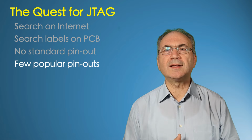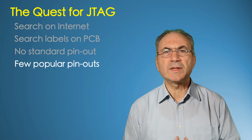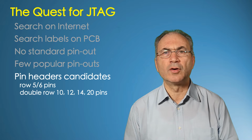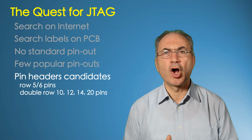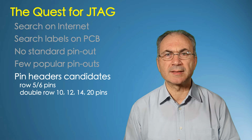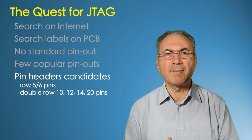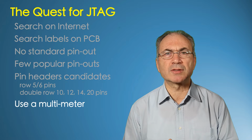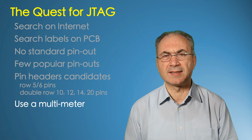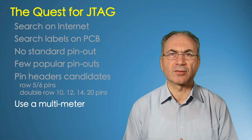If we don't find any JTAG pin label on our board, we start searching for pin headers arranged in a single row of 5 or 6 pins or in a double row of 10, 12, 14 or 20 pins. When we have found the pin candidates, we can use a multimeter to find the possible pinout, because finding ground and VCC is easy. Usually TMS and TDI have a pull-up resistor.